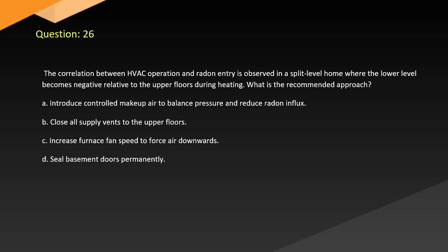Question 26. The correlation between HVAC operation and radon entry is observed in a split-level home where the lower level becomes negative relative to the upper floors during heating. What is the recommended approach? A. Introduce controlled make-up air to balance pressure and reduce radon influx. B. Close all supply vents to the upper floors. C. Increase furnace fan speed to force air downwards. D. Seal basement doors permanently.